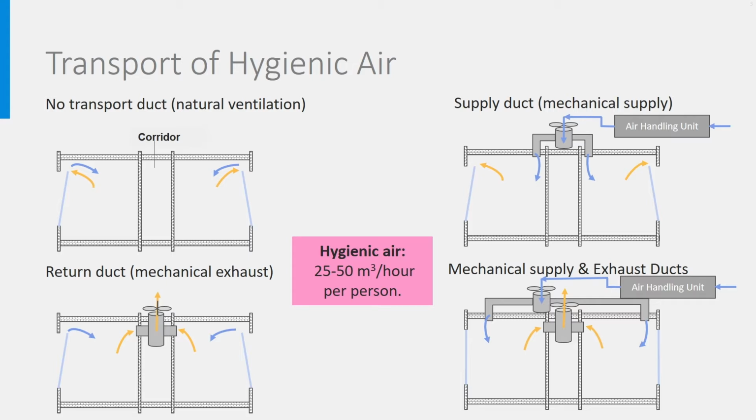So, in three of these systems, pipes are needed to transport air. The more air is needed, the bigger the pipes. For an architect, it is extremely important to know already at the start of the design how big will be the pipes. He has to account for them in his spatial design and reserve enough space for it. So, as an indoor climate designer, one of the first things you'll have to do is to make a choice between one of these four systems and to estimate the size of the pipes, if any.